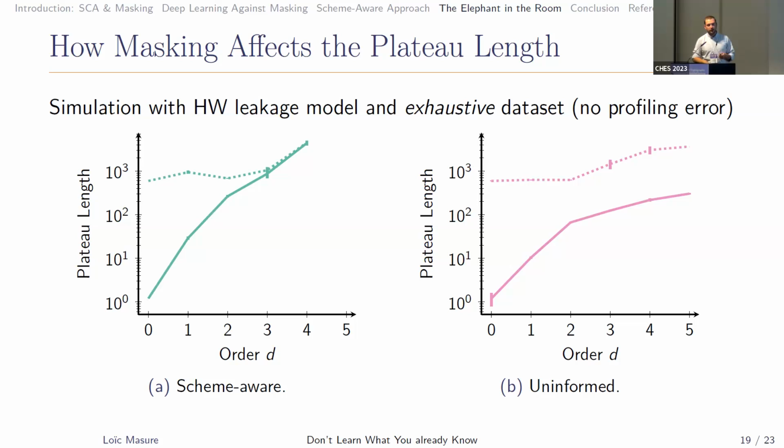And if you attended my colleague Torben's talk yesterday, you would be aware that in such a case, noise-free with Hamming weight, regardless of the masking order, we will still leak at least 1 bit on the secret. So we can run the experiments and increase the number of shares while still having something fairly comparable from one order to another.